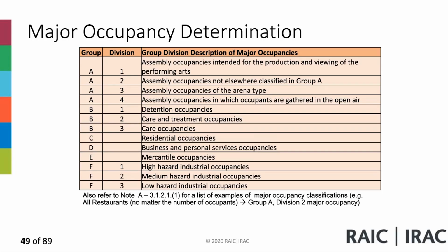And F2 could be an F10 or vice versa. It's really about the F1. You've got the list of F1 in the appendix. And F2 could be an F1 because it meets one of the listed occupancies under F1. But there's also a definition for F1, and you've got to take a look at the definition of F1, and then you know what hazards meet the definition of F1, and that's why you differentiate it.